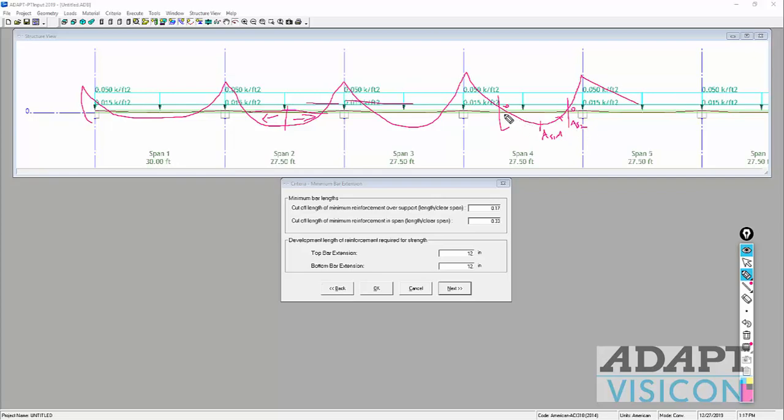The program might require bars to run from 0 to 0 plus the extension that meet AS2 plus another 2 bars that extend past that AS2 mark. And the program's algorithm usually will cut bars into 2 different segments like that to try to economize the design rather than just running the requirement for AS max beyond point of 0 moment. That's what this cutoff is here.